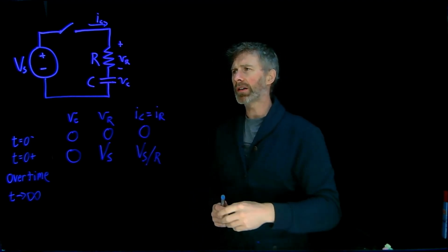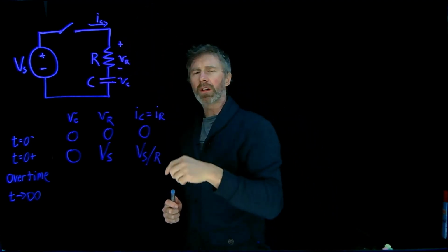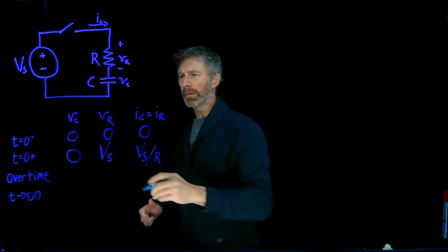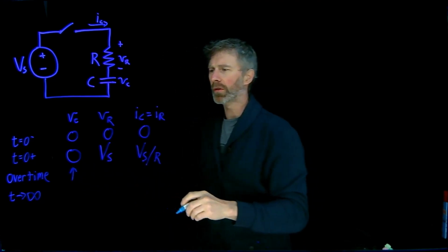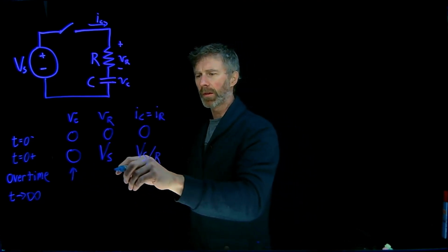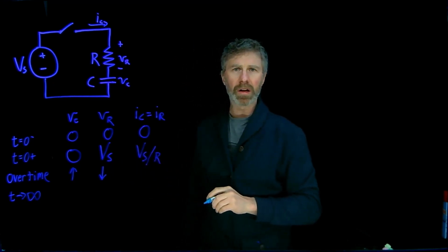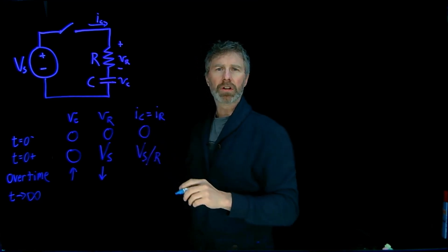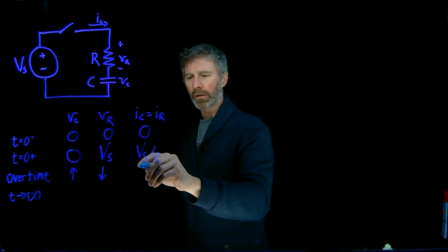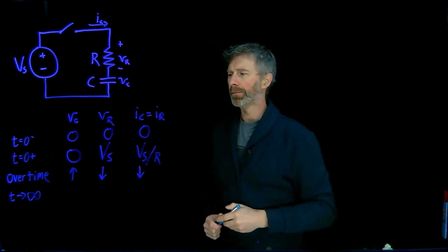Then as time progresses, current's going to flow into the capacitor and charge is going to build up. As charge builds up, so does voltage, so voltage is going to start increasing. And again, to keep Kirchhoff's voltage law true, VR has to go down now. If the voltage across the resistor is going down, then the current through the resistor is also going down.